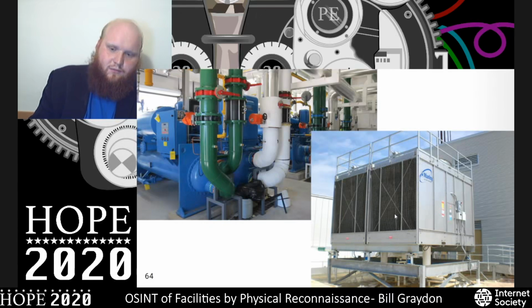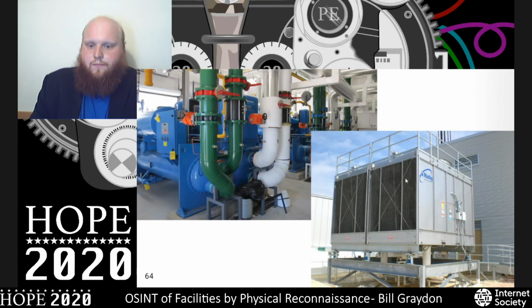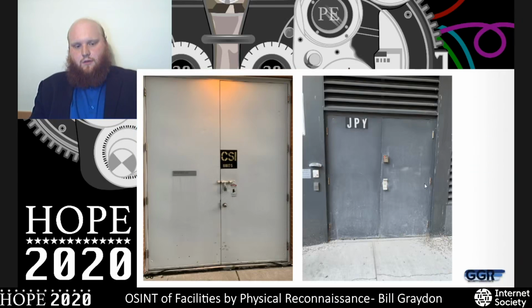And those boxes before, which I erroneously called air conditioners, are actually just cooling towers as well. This will feed a chiller that looks like this and is usually going to be in the mechanical penthouse below it. And by the capacity of these cooling towers, you can estimate what the cooling requirements for that building are, which gives a sense of occupancy and activity level.